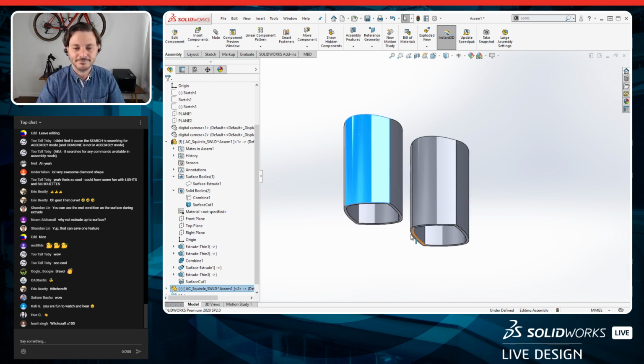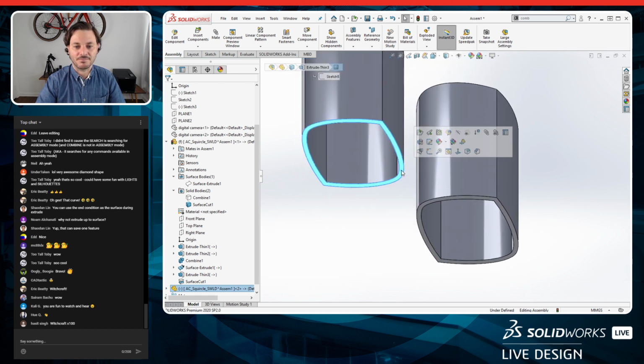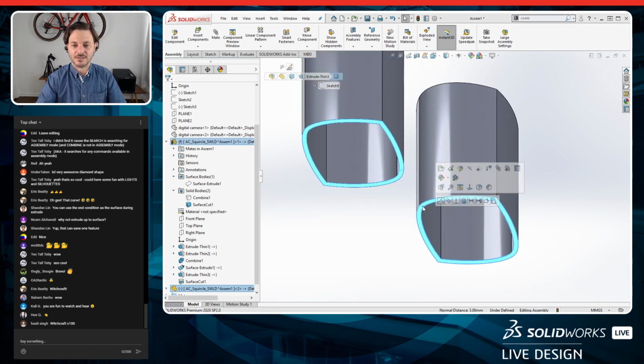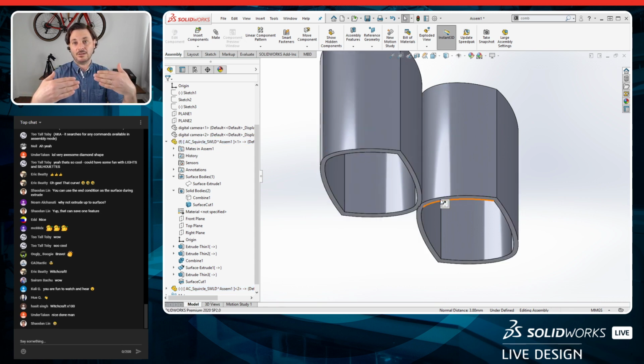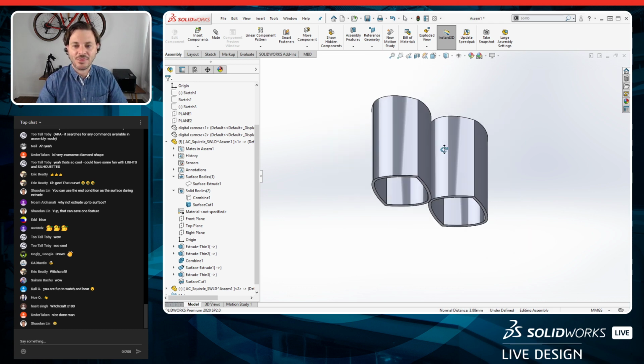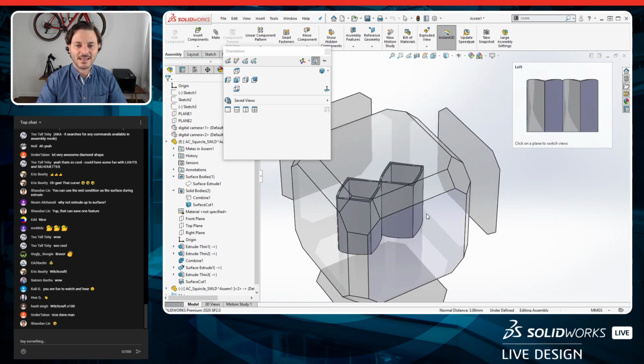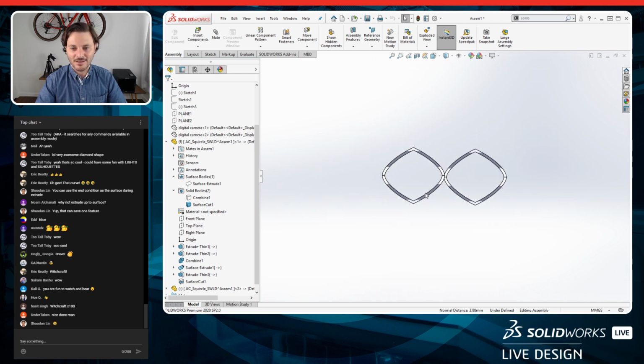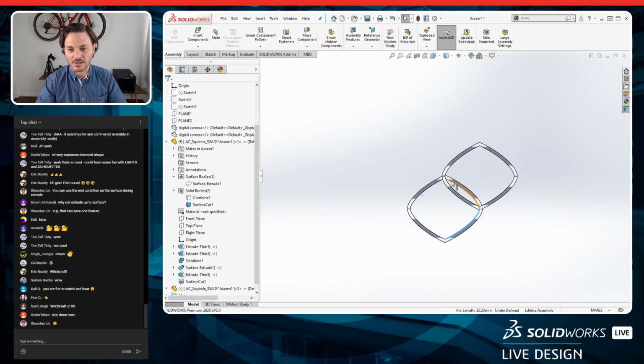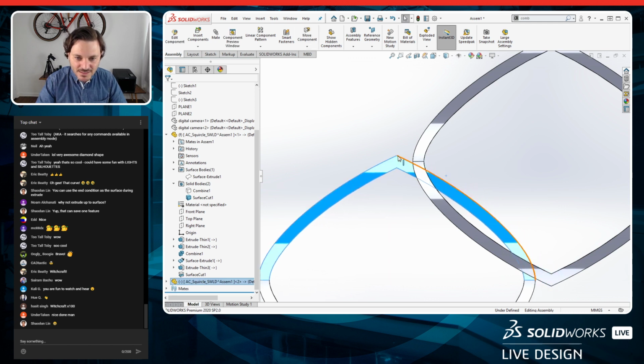All right, I'm just going to control click these 2 faces and use my Quick Mates toolbar like I used before. I want them to be coplanar. So now is when things get, like before, a little bit more loosey-goosey. Well, I know I kind of want these points, if there's an imaginary line between these 2 vertices, if I could visualize the midpoint there, I want that midpoint to line up with the midpoint of this edge. That's what I want to do.